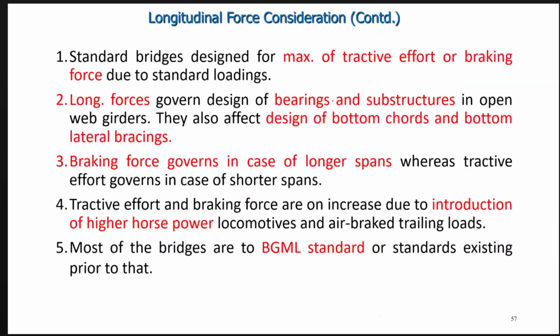Here we will discuss that a standard bridge is designed for the maximum tractive force or braking force due to standard loading. Longitudinal force governs the bearing and substructure. So mainly the longitudinal force is important for the bearing, specifically the holding down bolts, where the base plate is holding, or the top saddle plate is connected with the girder. That bolt transfers the longitudinal force, so it has to be checked.